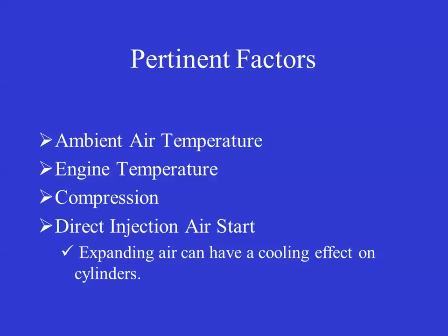The other part of that is your lube oil temperature. If your lube oil temperature is quite low, then what will happen is you'll have more resistance because of the higher viscosity. If the oil is cold, it's going to be a higher viscosity, more resistance to be able to turn the engine over, and then that means a slower turning speed on the engine, and that will affect the ability for the engine to start.